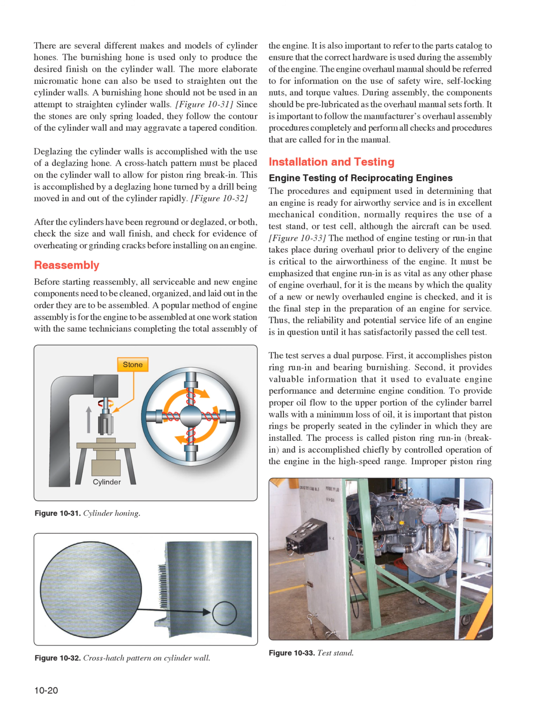Reassembly. Before starting reassembly, all serviceable and new engine components need to be cleaned, organized, and laid out in the order they are to be assembled. A popular method of engine assembly is for the engine to be assembled at one workstation with the same technicians completing the total assembly of the engine. It is also important to refer to the parts catalog to ensure that the correct hardware is used during the assembly of the engine. The engine overhaul manual should be referred to for information on the use of safety wire, self-locking nuts, and torque values.